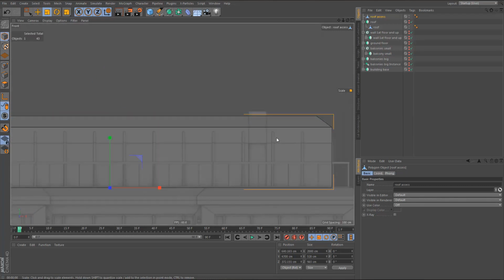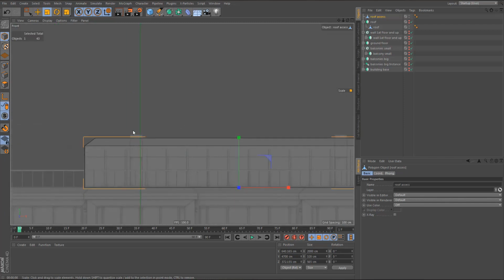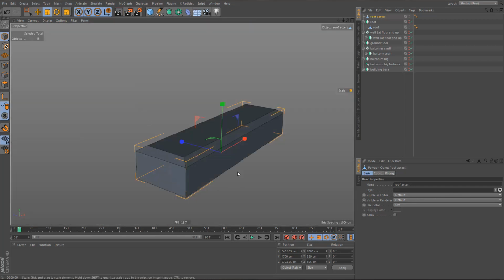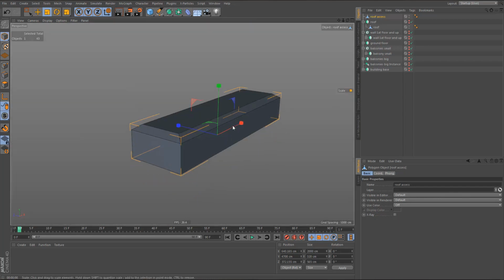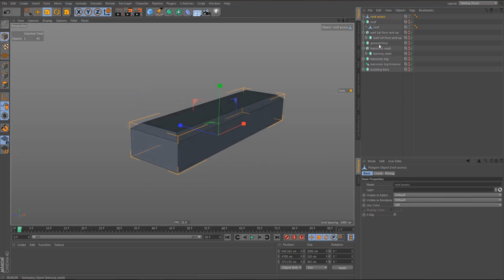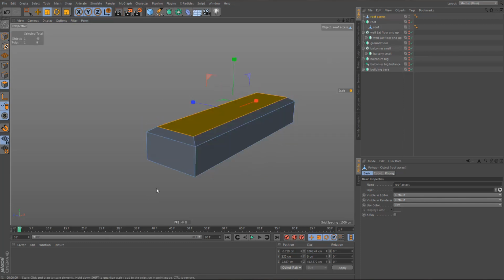And we also have these bars, and we have a couple of doors in there, and the extrusions on the top. And I'll start by adding the bars. Well, let's start by creating the bars first, and then we'll figure out how to copy them along this roof axis. Let's go to polygon mode. I'll just select this polygon and split it off. And this is going to be the roof axis bar.